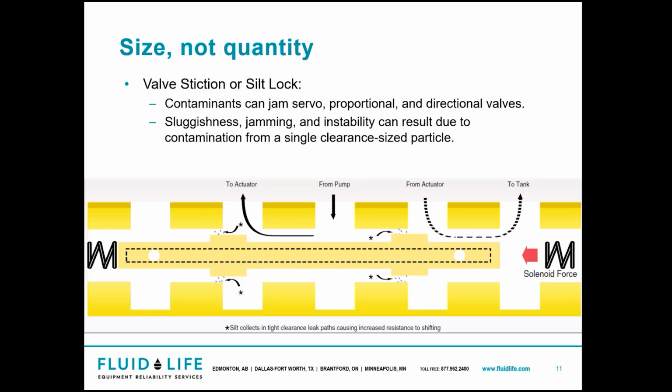You can see what I'm saying about how important it is to have that clean oil from the beginning, especially for systems that don't have some sort of online filtration system. It's going to be even more imperative. Filtering that oil before it goes into the machine is going to be a huge benefit.